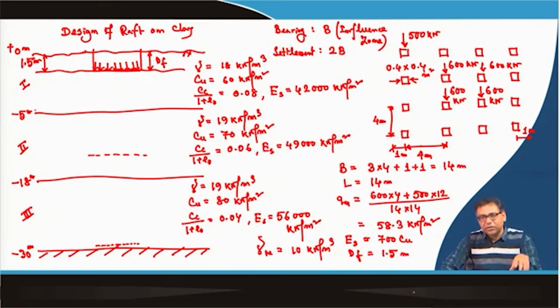Okay. So, the theory that I have discussed is for 2 layer soil. Even for a 3 layer system you can convert it to a 2 layer system. That is not a problem, because if your bottom layers are very soft, you can take the weighted average for the bottom layers and make one soft bottom layer, and for the stronger layers in the top you can take the weighted average and make it 2 layers.